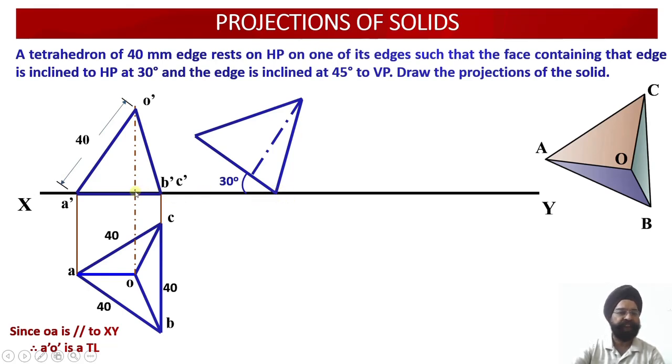Measure this distance between point 2. I'll get the second point. From the second point, draw the perpendicular distance, measure this distance over here. So the distance of this locus point 2 with O dash, I am going to mark this point. So this O1 dash will be located. And then go straight and mark point 3. So measure the distance and mark it over here.